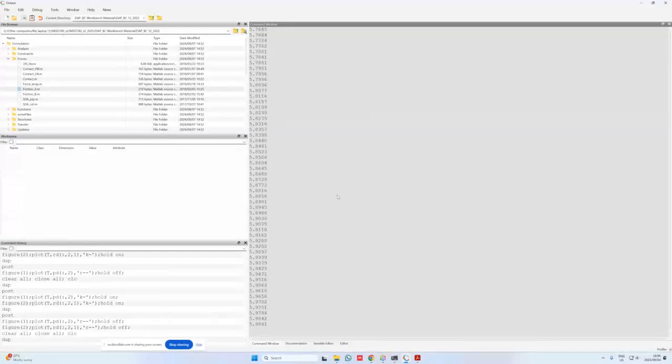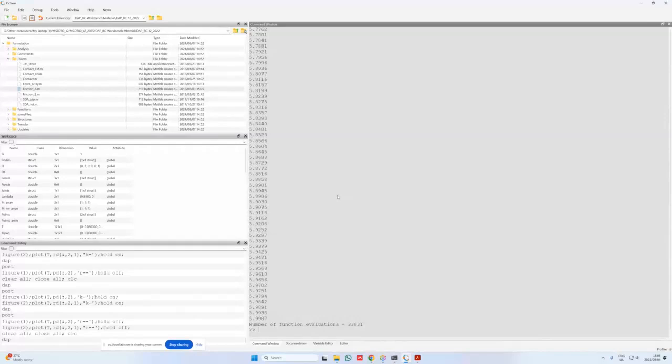But this is also the nice thing about a variable time step integrator, such as the ODE45 that we're using. It's able to vary the time step based on the level of accuracy that I need in the system. So although it's taking very small time steps at the stiction phase, it's going to take larger time steps after and before the stiction phase that I have in the system, which makes it a bit more computationally efficient.